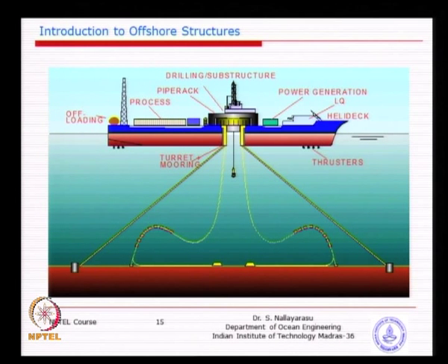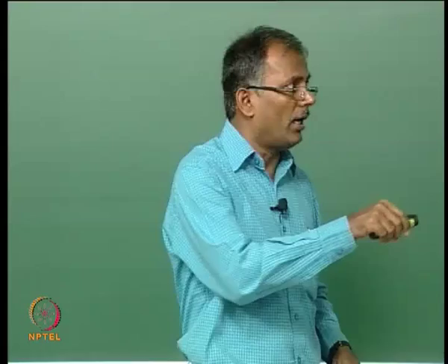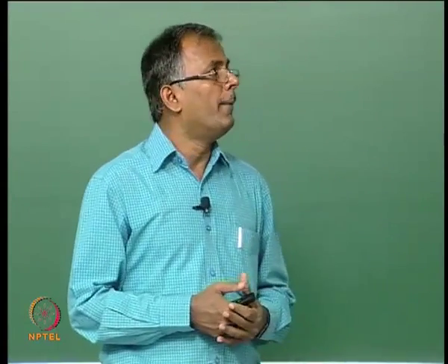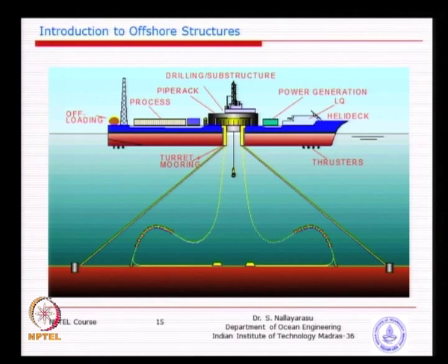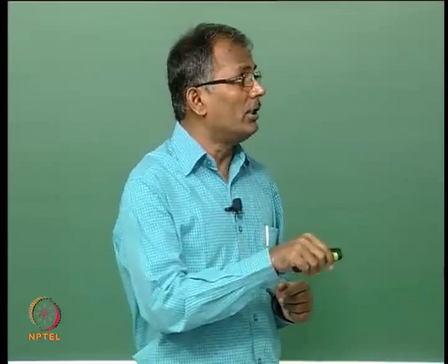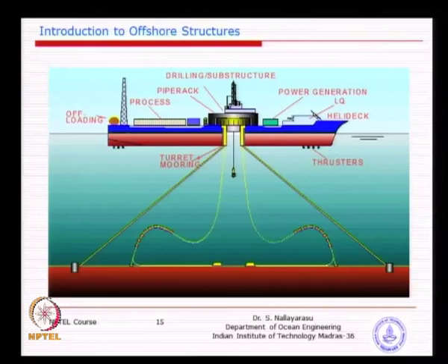So, the only problem with this system is the connectivity between the seabed and the ship. For example, you have a riser typically transferring oil produced by this FPSO, and it has to go through this and then go to the land. Now, this connection between this line and the ship, because the ship is rotating, imagine it is not a fixed part. So, you have one line coming, but it needs to have a swivel. That line also needs to rotate all the time, otherwise it will just break. So, that is one of the difficulties: designing a rotatable and leak-proof connection between a pipeline coming from the seabed and the ship is a big challenge.